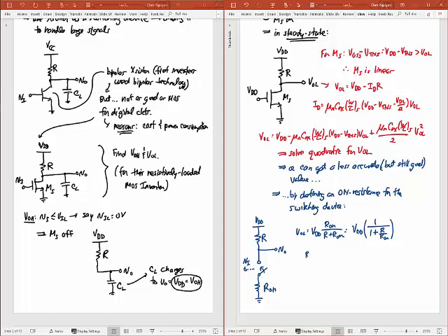And R on then, the best thing to use is just use the current that's running through that transistor. Okay, so define R on as whatever the VDS is for that transistor divided by whatever its current is, ID. And so in that case, the VDS is going to be the voltage dropped across MS. That's going to be VOL, right? And so I'm dropping VOL across this. And so the VDS here is effectively VOL. Okay, and that I'm going to divide by the current going through the transistor.